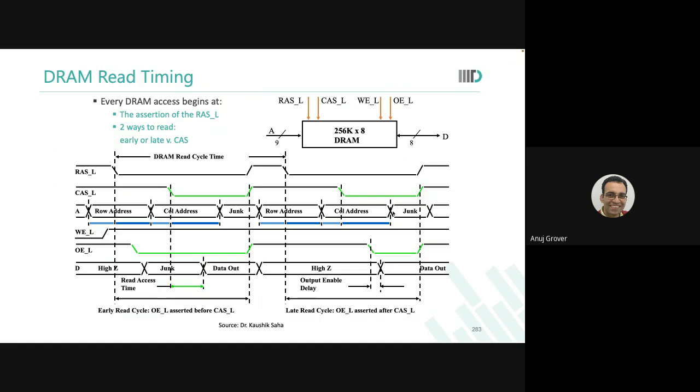Now you are hoping that all the write requests to the DRAM will be spaced sufficiently apart so that while I am putting some data in the buffer, by the time the next request will come, the buffer would be empty. I would have written all this data into my DRAM. So how much ever time it takes, I have written a buffer. So my DRAM write is non-critical.